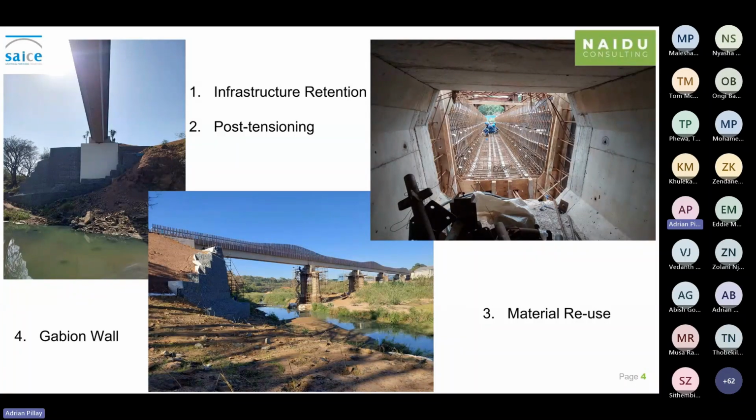The structure comprised a continuous composite post-tension beam and reinforced concrete slab deck, consisting of adapted U-beams and a 350 millimeter thick reinforced concrete top slab. The continuous U-beams encase the gravity sewer line, comprising a structured wall HDPE pipe. The selection of the HDPE pipe was based on its reduced weight, which was vital in reducing the load on the existing bridge structure. The HDPE is also inherently flexible and can withstand larger deformations and deflections than rigid and brittle pipe materials.